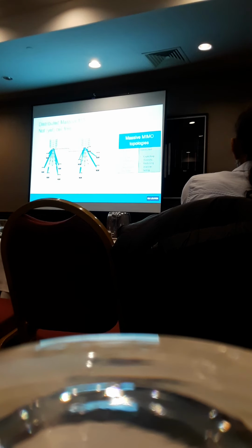First of all, there's the basic idea of, let's say you want to serve users in one room. You have a panel of antennas on one side. This is a normal collocated scenario. But what if there's a wall in the middle of the room and you walk behind that wall? Of course, this will influence the performance of your system. But what if you distribute your antennas all around the room? Then there's actually no line of sight scenario. So that's quite a big improvement. We're reducing the shadow fading, and on the other side, you also introduce more diversity. So you're able to distinguish your users in a better way, but more on this later in the figures.